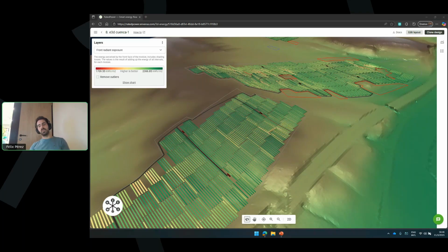Because when a module is uniformly illuminated, with no shading, we just run the calculation model, the one diode model, once per module. But if you have partial shading, we may have to run the one diode model like 6 or 8 times per module that's shaded. So that increases the calculation time a lot. But I'd say that mostly it's PV plant size. The tracking doesn't have an impact, for example. So in that sense, it's pretty cool.